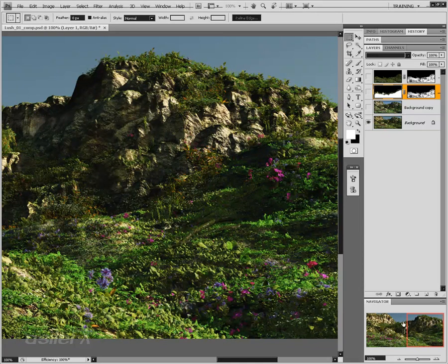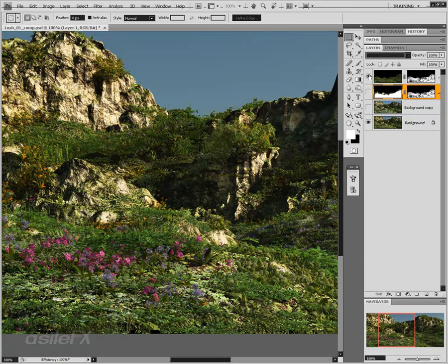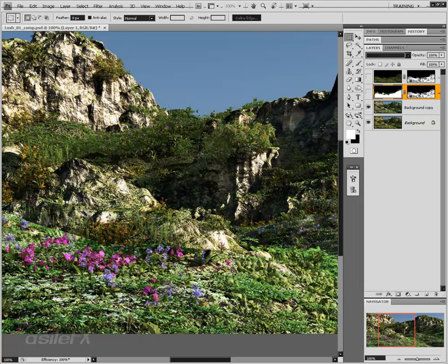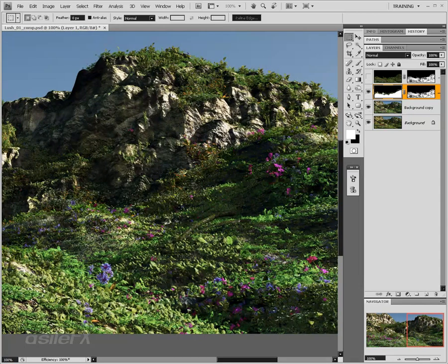Since some of the seams were showing up so much, and we can really see some harsh lines between the two different terrains, what I did was go back to the first render I did with all the vegetation and the full coverage and took out that render pass where it's just the ecosystem. After making a few color changes to the main render, I then just took a mask using one of the available masks, changing it a little, but basically just cutting out the ecosystem along those seams where originally it was covering up that back terrain. And of course, in a few places, leaving it open.